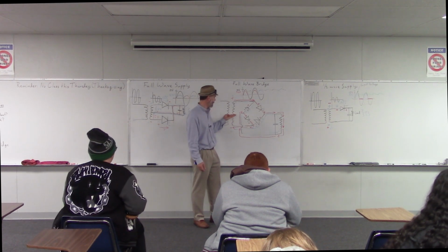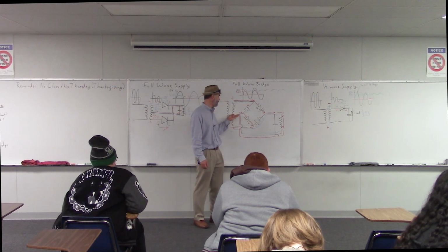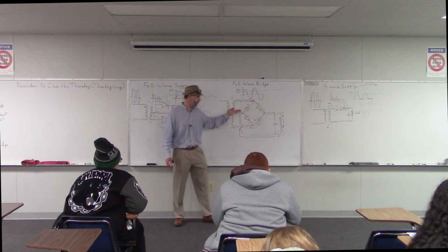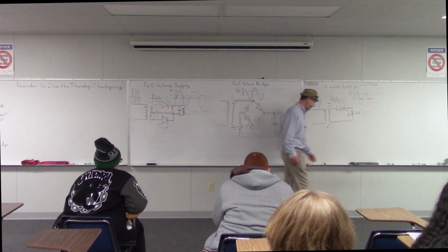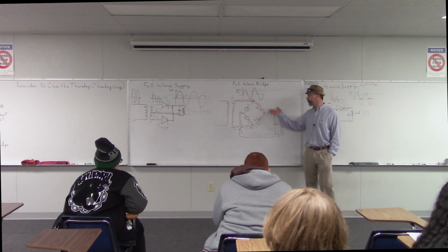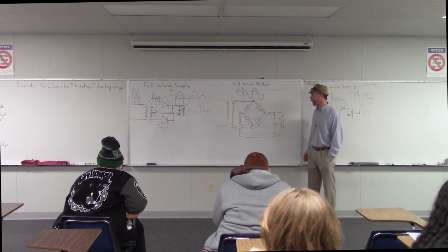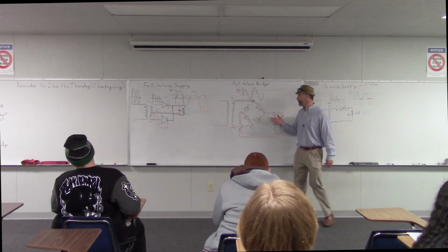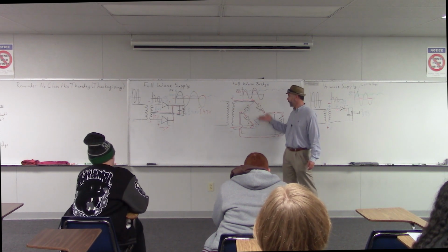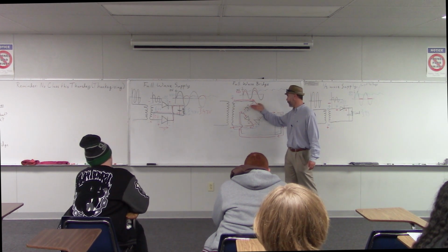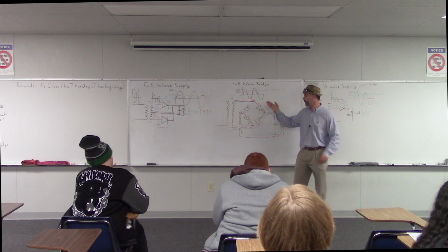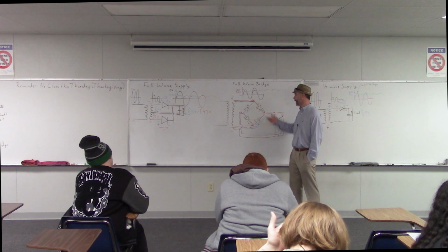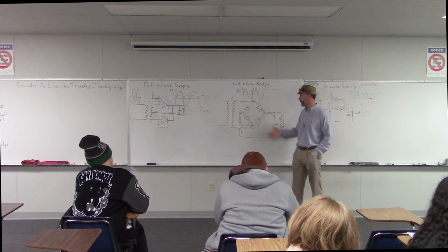Fortunately, it does not have that center tap anymore, so we don't have to spend the extra money on that. You do on the diodes. Right, you do on the diodes, but this type of rectifier is so common that some chip manufacturers actually make a chip that has these 4 diodes built in, in this configuration. So rather than buying 4 separate diodes, you can just buy that chip because it's so commonly used that way.